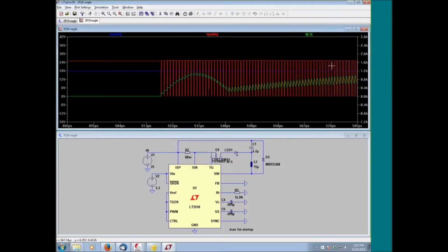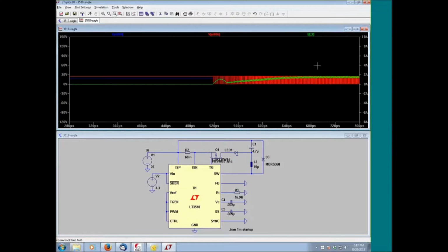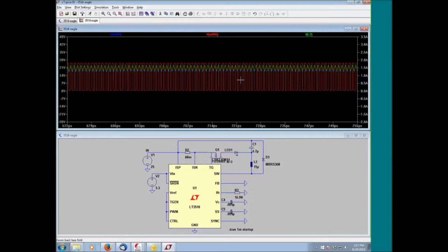we see how the duty cycle starts to adjust to keep that current increasing up until we get to the point for the current that we want to have here, up to our steady state current. So now the duty cycle has stabilized. That's our ripple, our current ripple. Now we can see that it's pretty accurately modeled how this part behaves in this regard.